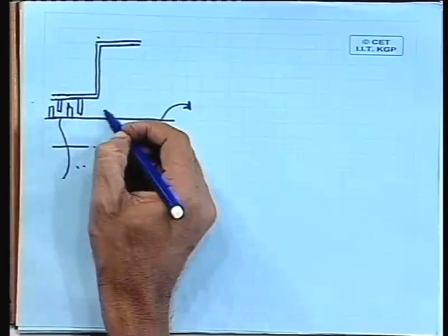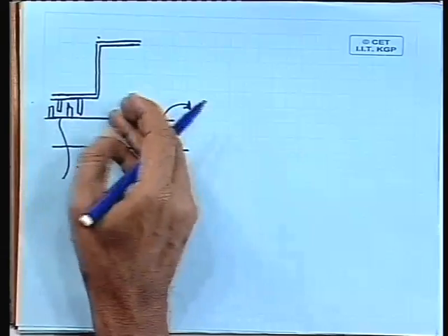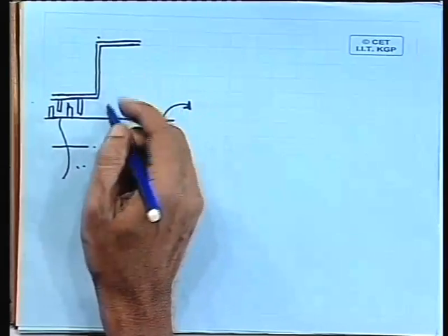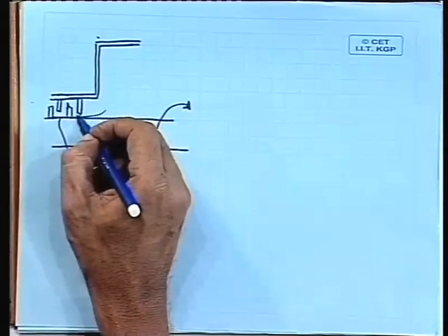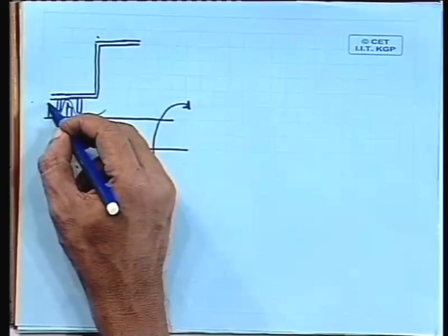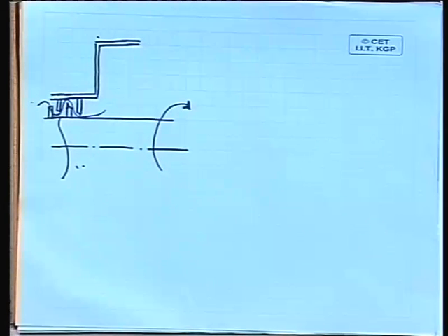So, between this point and this point there is obviously a pressure difference, but if this steam has to flow, then it has to flow through these zigzag passages, and as there is a large pressure drop, the leakage will be minimized due to this particular design. So, this is known as gland or gland sealing.